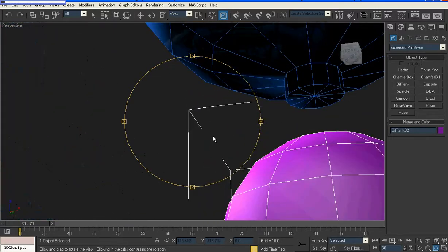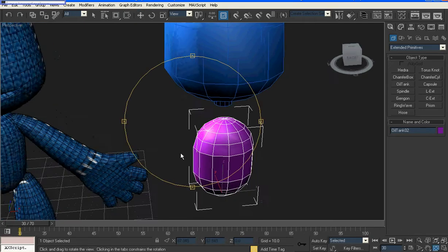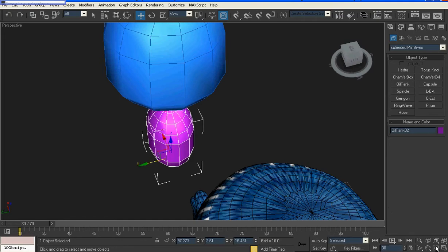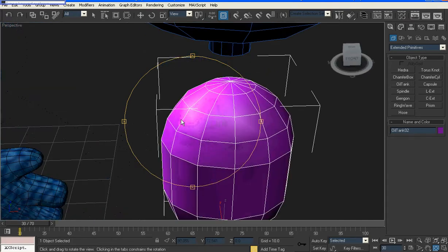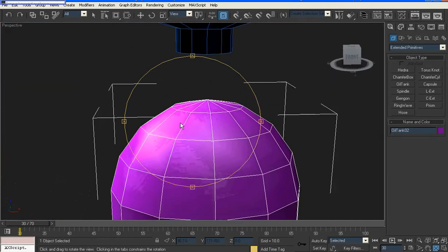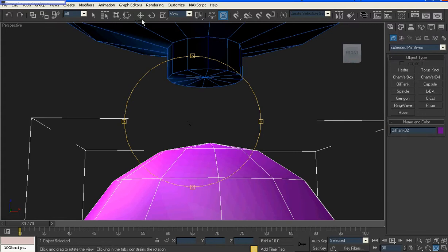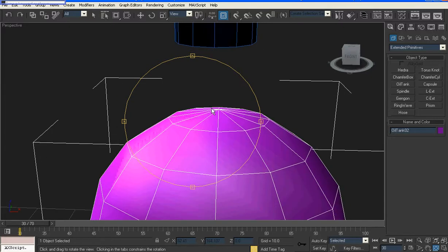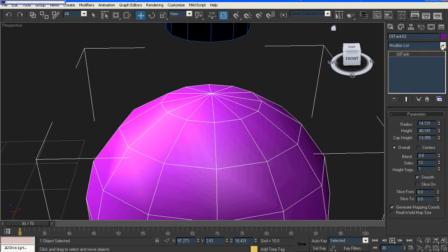And what we're going to be doing here is learning a new skill, which actually you should have learned in yesterday's lesson. So it's actually not a new skill. We're going to be spiraling that skill that we learned yesterday, which is how to attach and weld. So we can see here that both of these oil tanks have the same top cap. So there's the same amount of polygons in the neck and in the piece that we're attaching to, right? So the first thing that you want to do is come into this new oil tank here and add an edit mesh modifier to that oil tank.